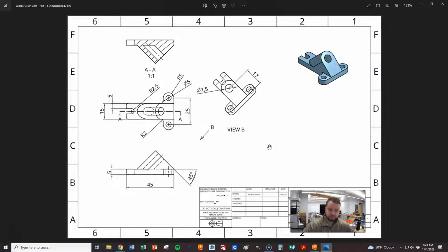Okay, so let's go back and look at this. There's a couple issues I've had with this. Obviously, it didn't give me this measurement, so that's wrong. And the second thing is, if this is one solid part, and let's say I had to drill this hole, looking at these hidden lines, it gives you this angled bottom. Well, that's okay. We could do that.